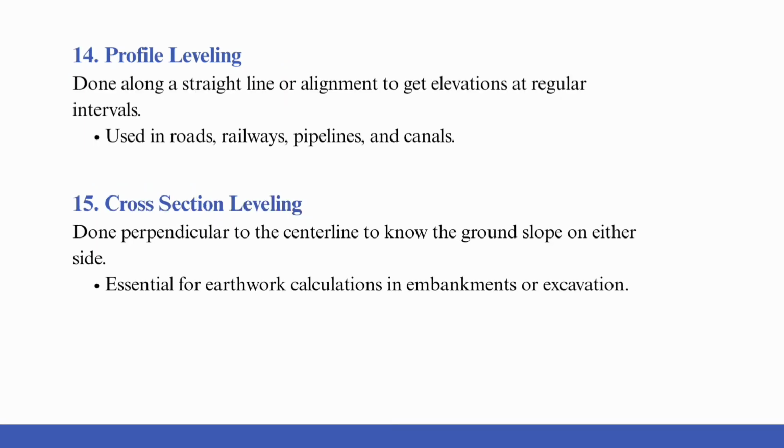The next type of leveling is profile leveling. It is done along a straight line or the alignment to get the elevations at regular intervals, and it is used in roads, railways, pipelines or canals.